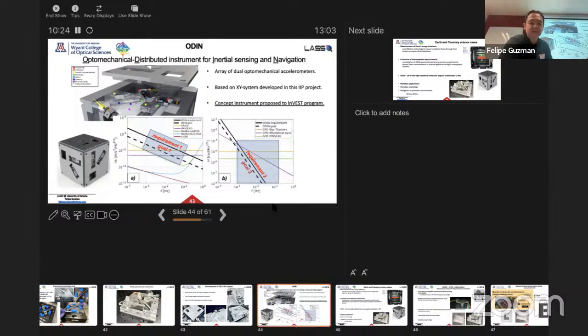Well, yeah, so let's look at this. This line here is a millihertz, so integration times of about 1,000 seconds. If you're relying on inertial navigation over 1,000 seconds, you're going to get very good sensitivity, better than what you would get with a fiber gyro. Now, this tells you how well you can measure angle. These are actually radians. So it depends on how well you need to know your orientation over time to be able to say if this is going to work out for you.